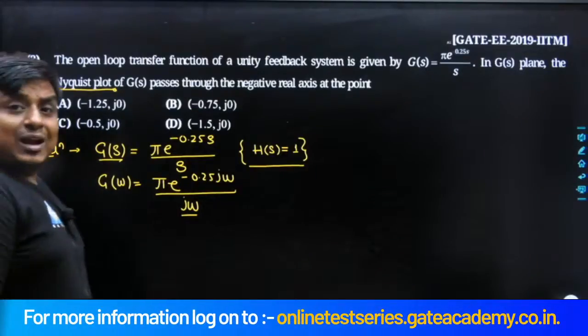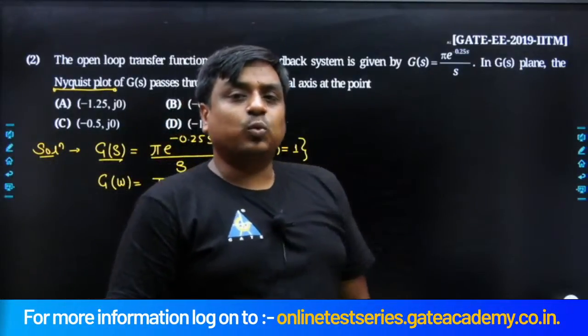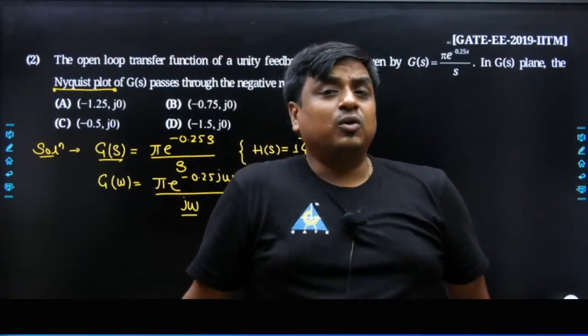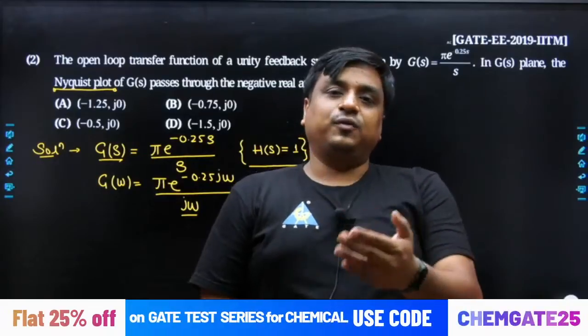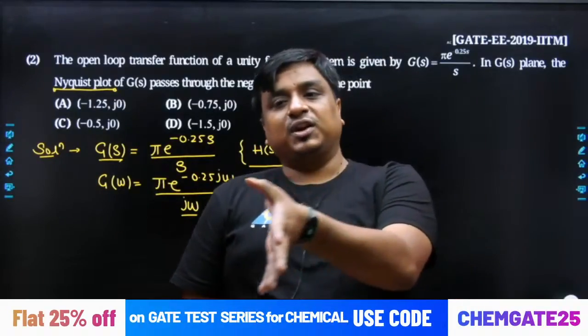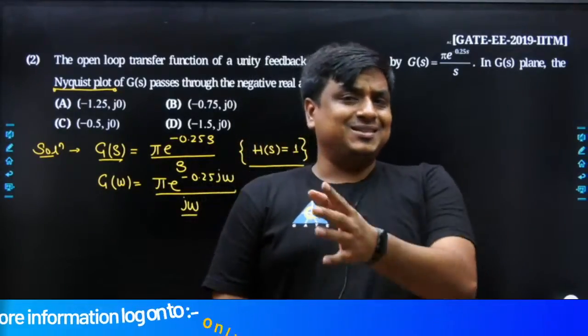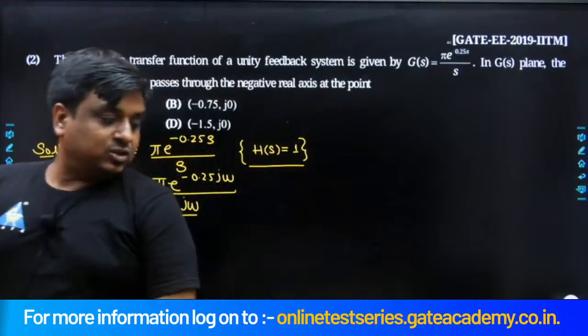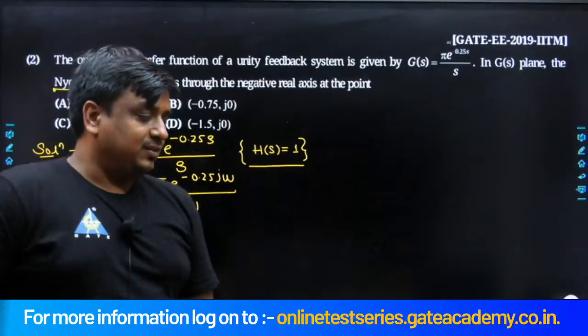So far for us the OLTF was G(s)H(s), but why are you now taking the reference of G(s) alone? My dear friend, when you are talking about the unity feedback system, by default H(s) becomes 1. In that case, either you can refer to the OLTF of the system as G(s)H(s) or simply G(s). Choice is yours. So the answers have started coming. As per Amit Kumar, the answer would be C.